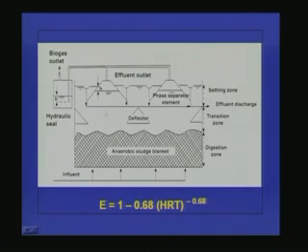So what will happen? The biosolids or the microorganisms will be in flocculant form, and whatever biogas is produced will also be sticking to the microbial flocks. So as such the density of the flock will be less, so everything will be rising up along with the liquid, because this liquid will be having an upflow velocity. So with the same or almost the same velocity, everything will be rising up.